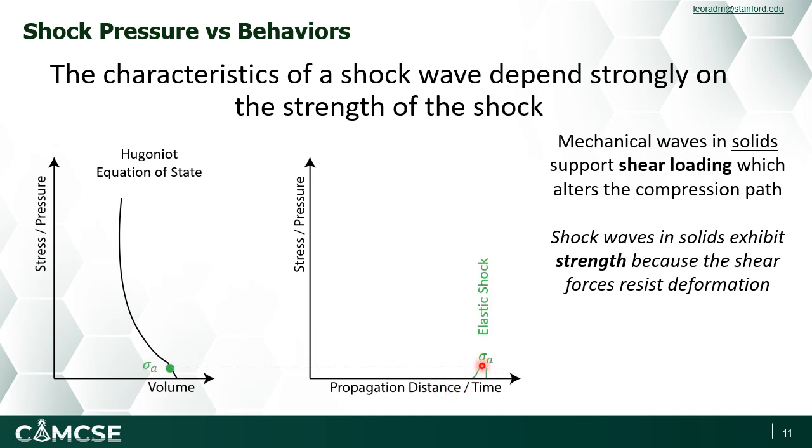In this type of single wave, we really are below what's called the Hugoniot elastic limit, at which point we would end up with a stress or pressure that actually would make the material fail. So in our Hugoniot equation of state, what we see is a linear trend here that eventually reaches a kink point that then starts to bend, as we've seen in our previous slides.